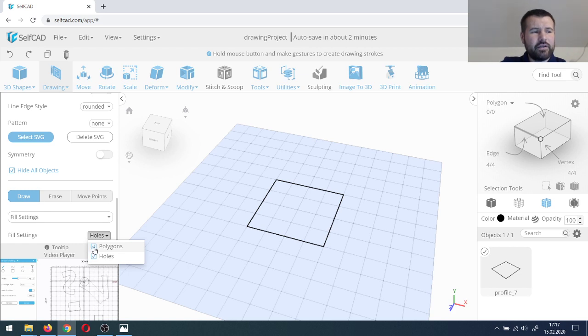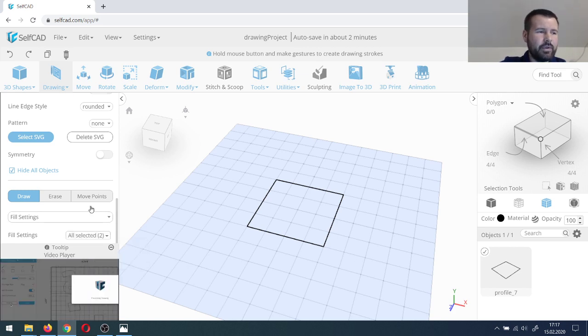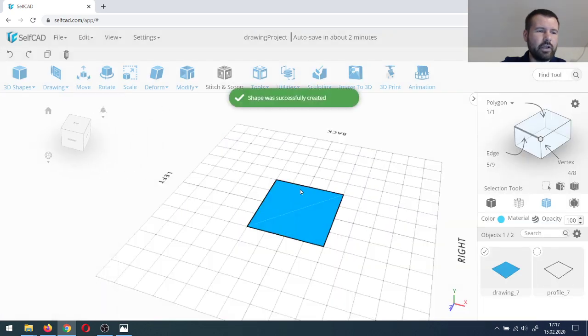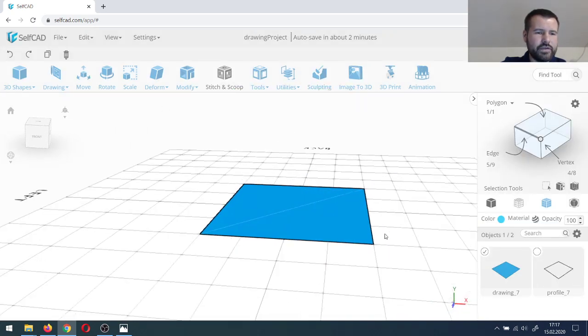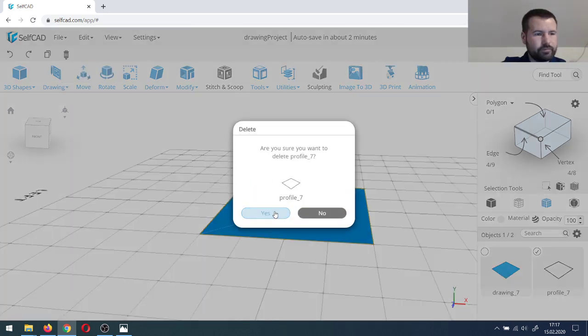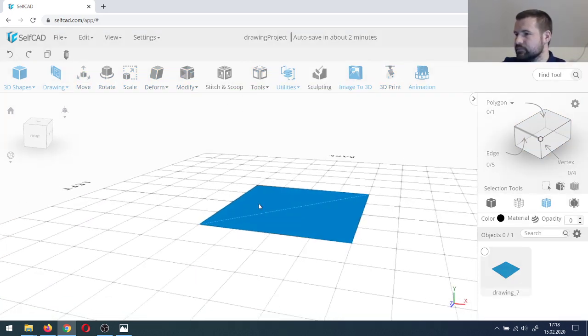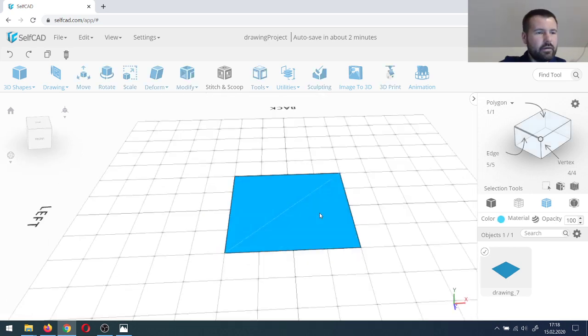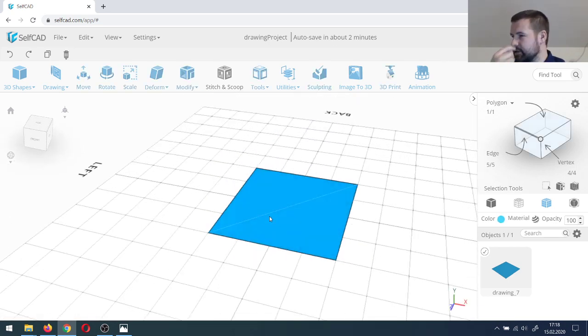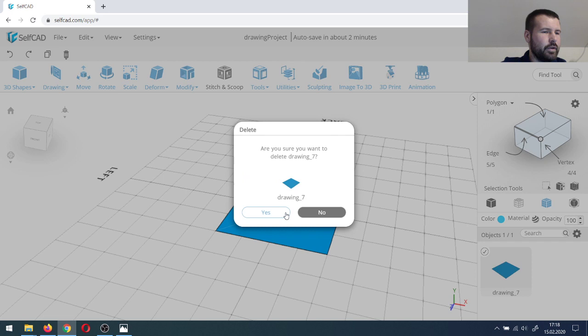But there is also this setting called polygons, and if you enable the polygons and finalize, you will notice that it actually converts the freehand drawing to surfaces. Okay, I see that we have a question. What's the difference between follow path and fill polygons?